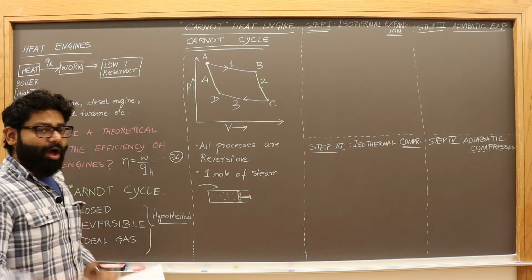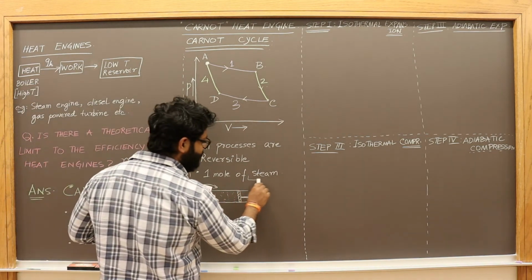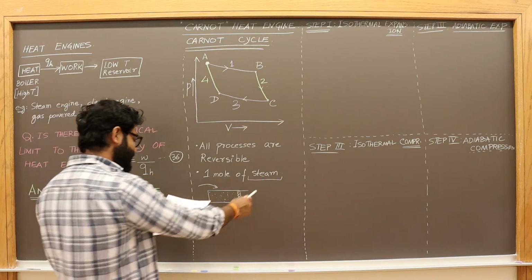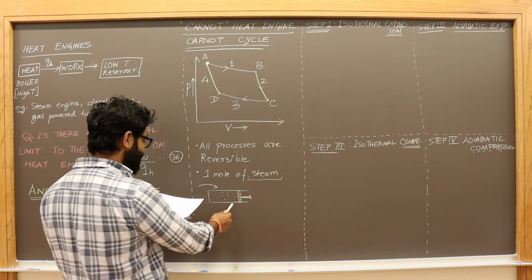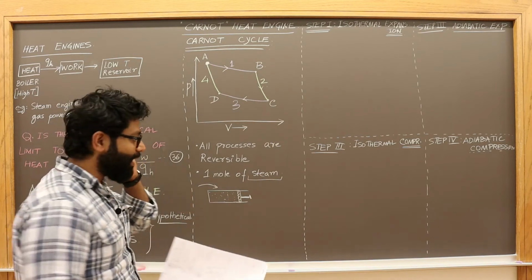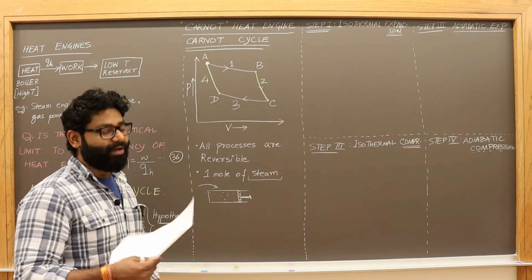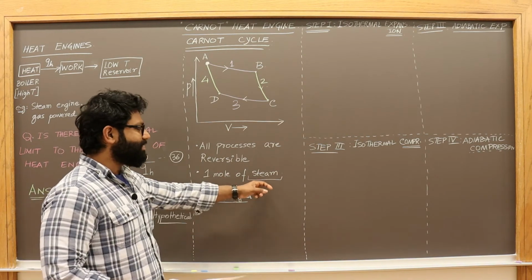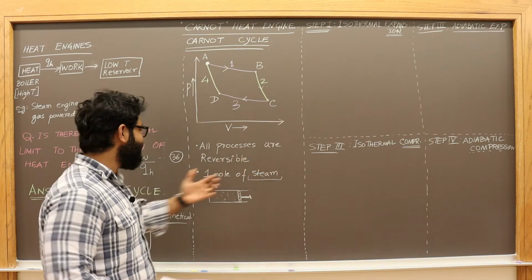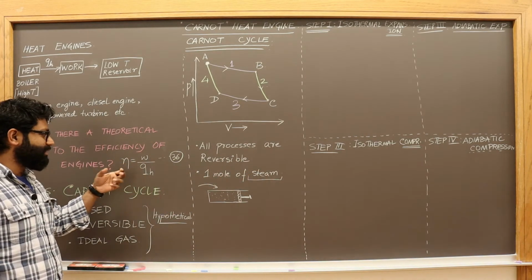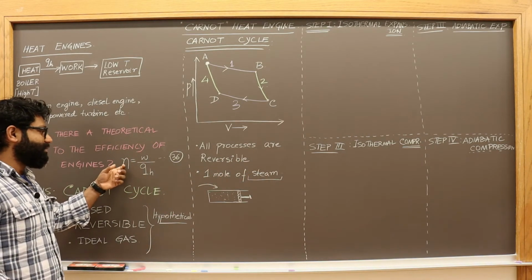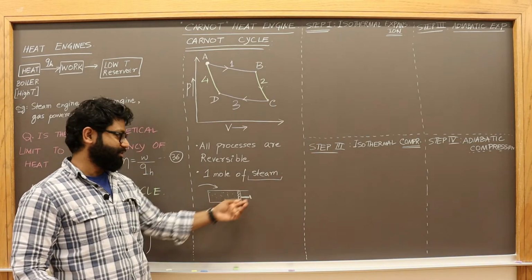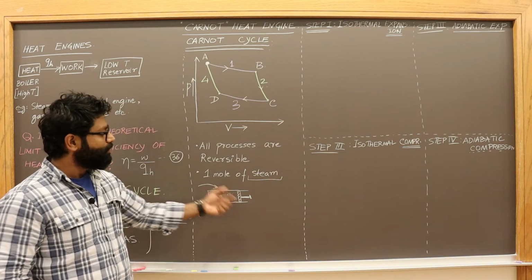Later on we'll see that the choice of the gas inside will not matter. Whatever you take, the efficiency of the engine will not depend upon whether you use steam or air or any other gas. We'll see how that happens. The final thing that comes in this equation does not refer to any of the material properties of the gas that is inside.